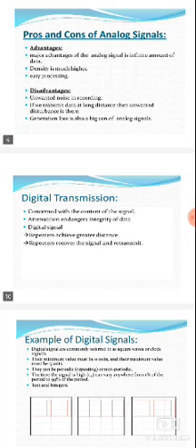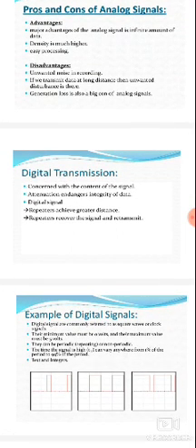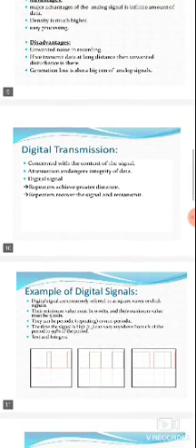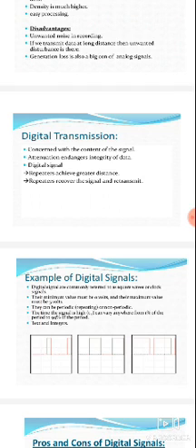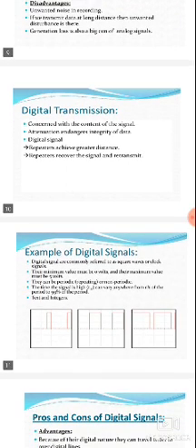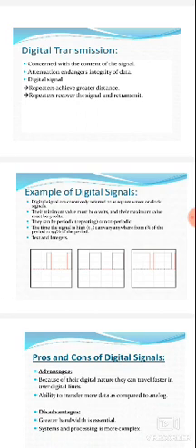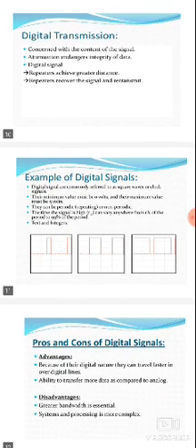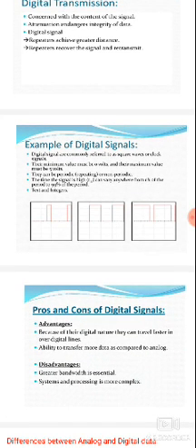Digital systems use repeaters for greater distances. Data transmission supports greater distances, and repeaters recover the signals and retransmit them. Attenuation endangers the integrity of data in digital signals. Digital signals are mainly examples of square waves. Square waves or clock waves occupy levels from 0 to 5 volts. They can also be repeating or non-repeating, that is, periodic and non-periodic signals.